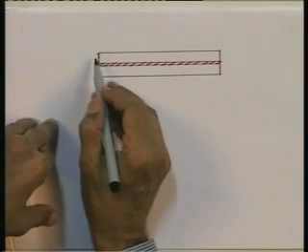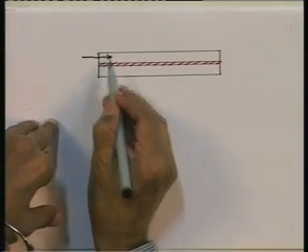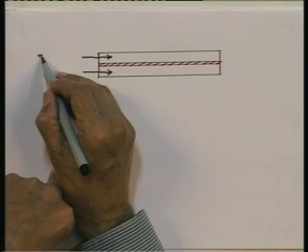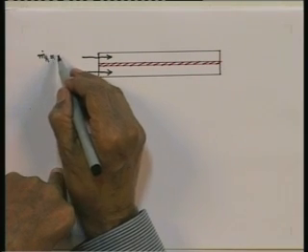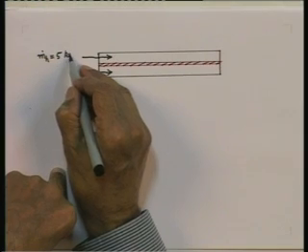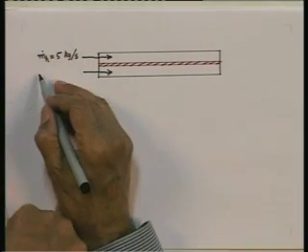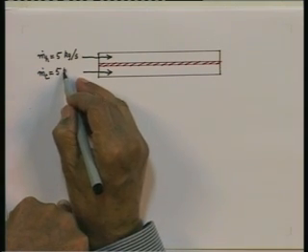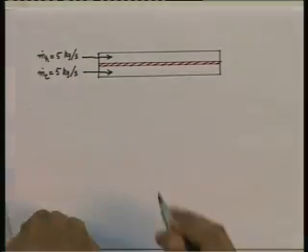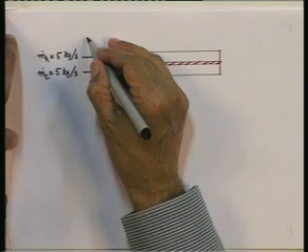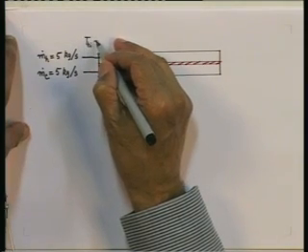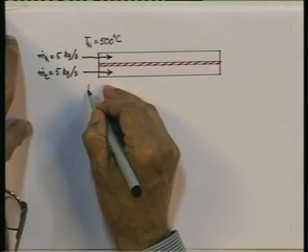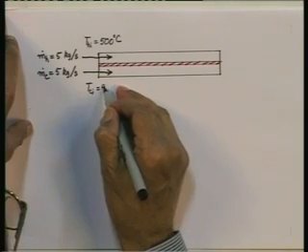The fluid on the hot side, it is a parallel flow heat exchanger, m dot h equal to 5 kilograms per second. m dot c is given to be the same, 5 kilograms per second. T h i, you are told the inlet temperature on the hot side equal to 500 centigrade. T c i equal to 90 degrees centigrade.